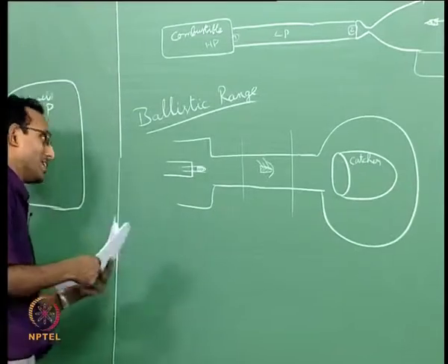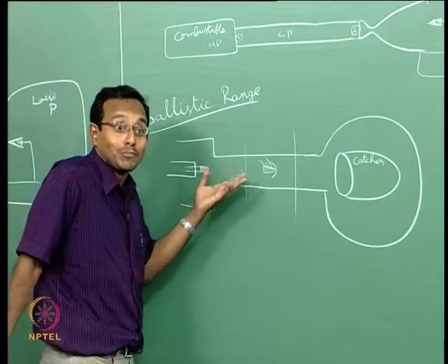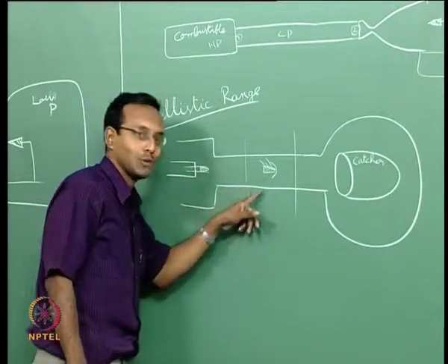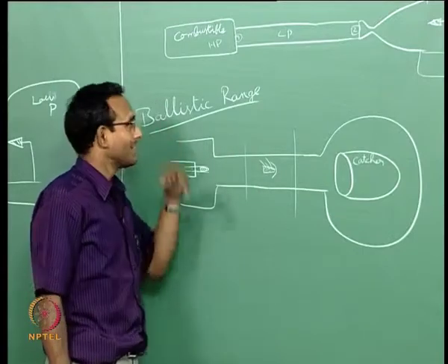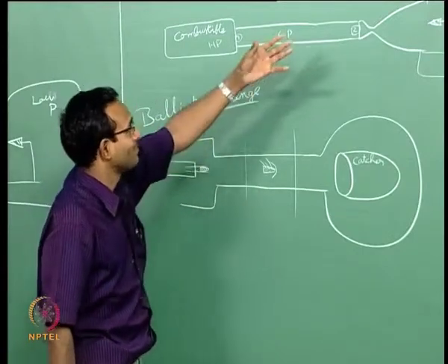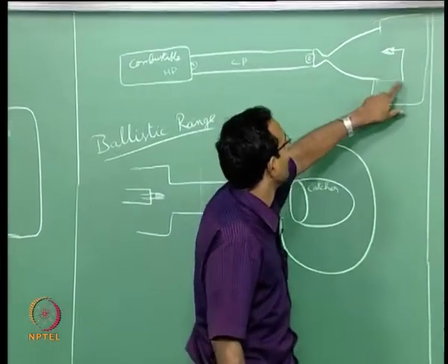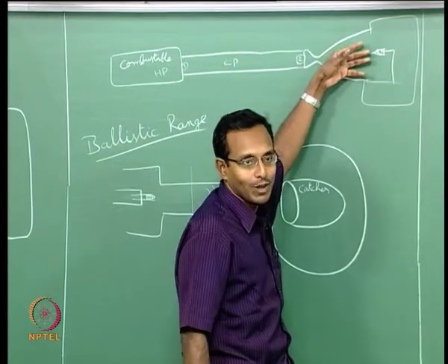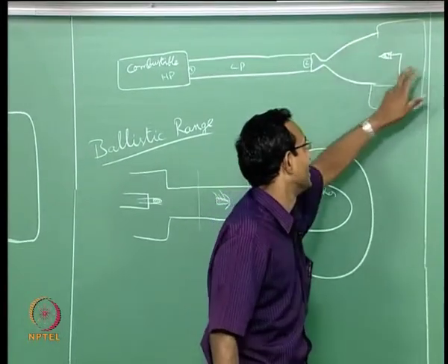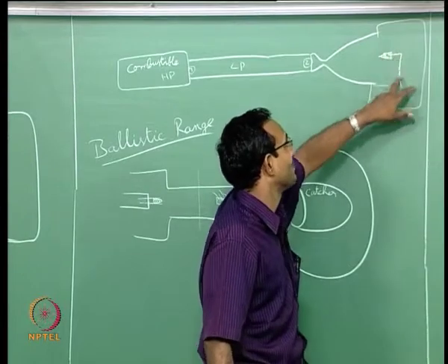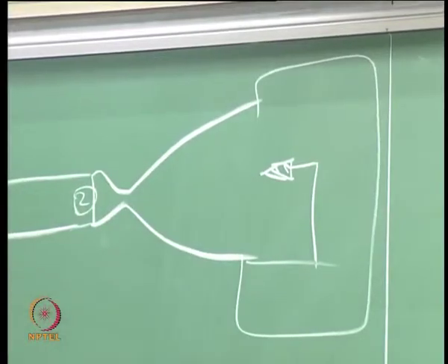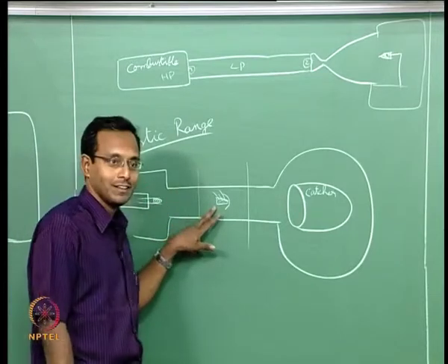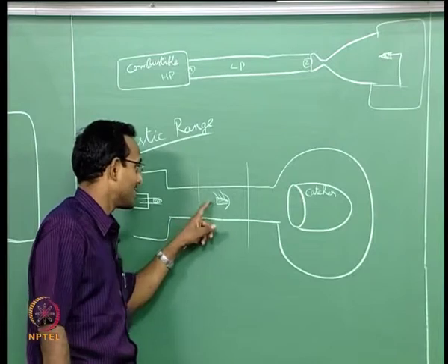Okay. The good thing about here is there is no support for the model, okay, which means there is nothing else which is going to obstruct the flow. In the other cases, I have to hold the model somehow. Say for example, if I pick this one, this is going to be sitting here, and it may obstruct my flow after some time. That is, the shock goes through and then it is going to reflect back, and maybe it is going to have some effect here. There is no such thing in this particular flow, and I can calculate the exact drag on this body directly by keeping track of how fast is it traveling through this point.